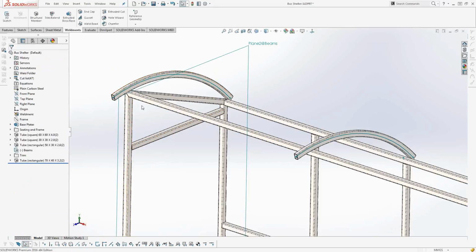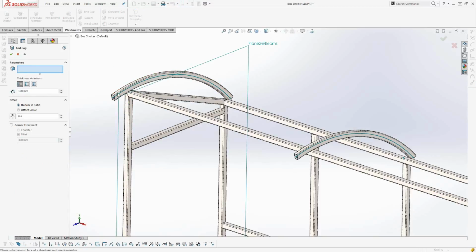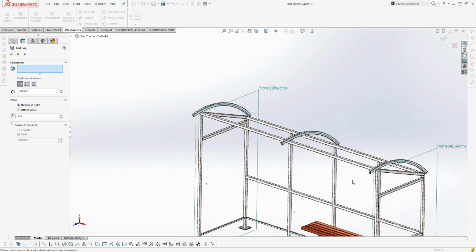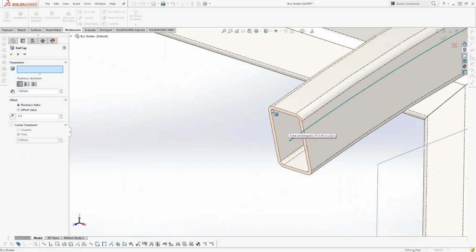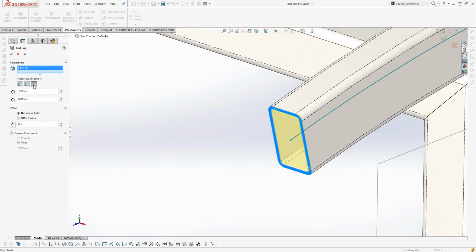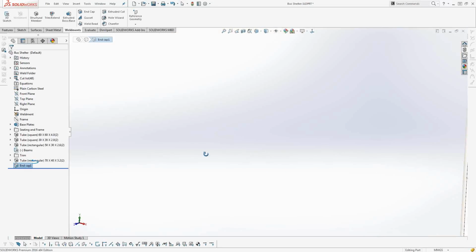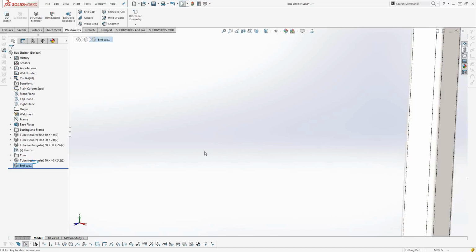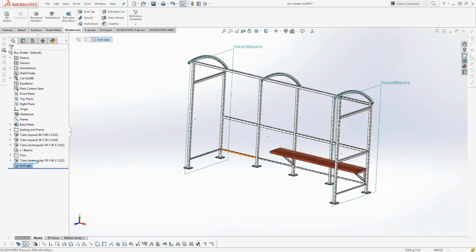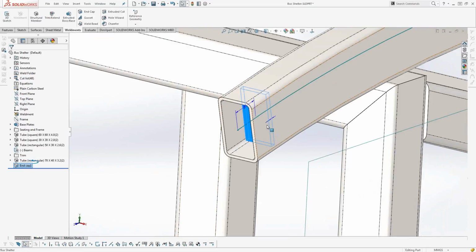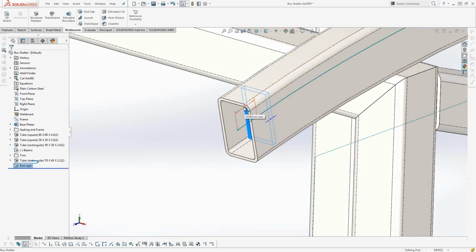They also made a couple of enhancements to end caps. Nothing incredibly huge here. If I come over to this part and decide to put an end cap on this face, we've always had the ability to create inset end caps and even produce an offset into the part. But what's new in SolidWorks 2016 is that all of those features are now accessible externally to the part. So as an example here, if I go back into my part and choose to double click on this, you notice that the thickness dimension, the offset dimension that's here, even on this curved entity, is available to me as a dimension. I don't have to edit these within the features themselves.